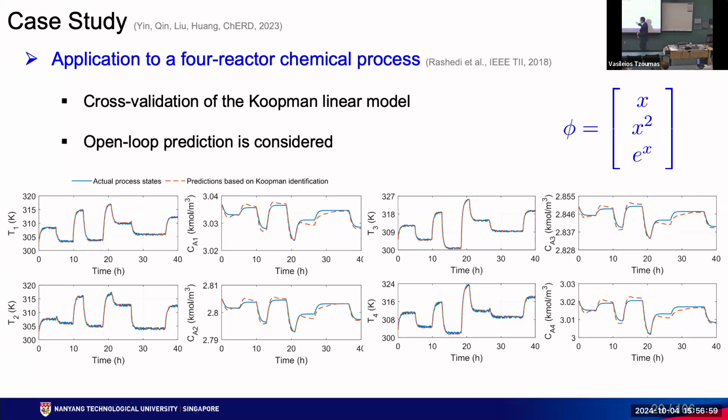And here is the modeling performance. And I would like to mention that this is an infinite step ahead prediction of the model error. We never updated the model prediction using any state feedback. So this is, I think, two reasons. So the most critical reason is that this system is open loop stable. And we have identified a stable A matrix for this process. I think that's why we can realize infinite step ahead prediction.